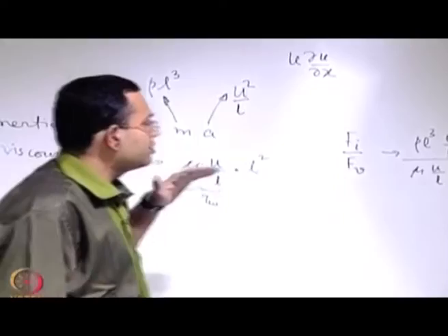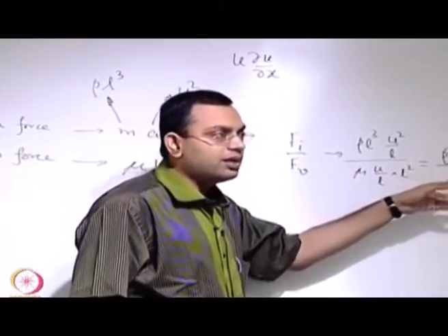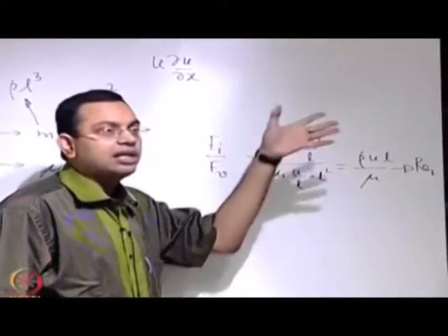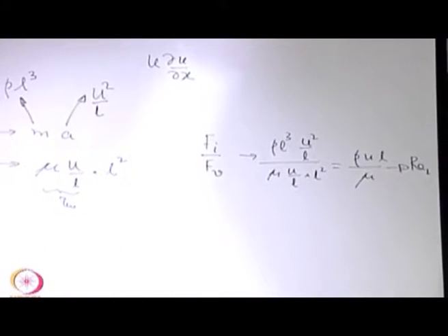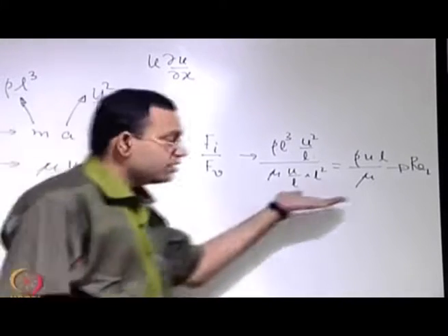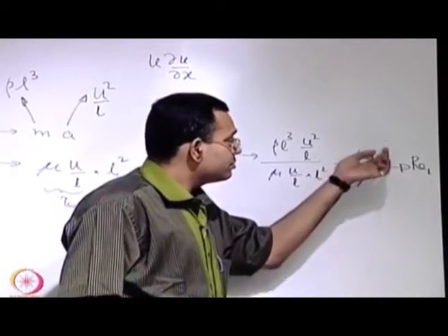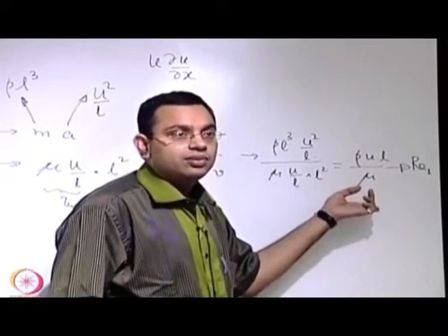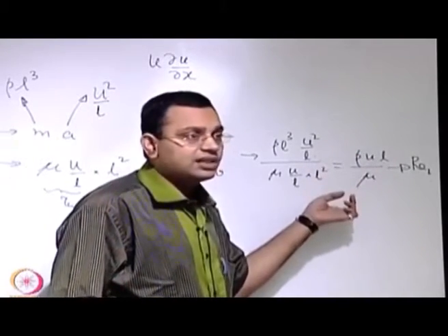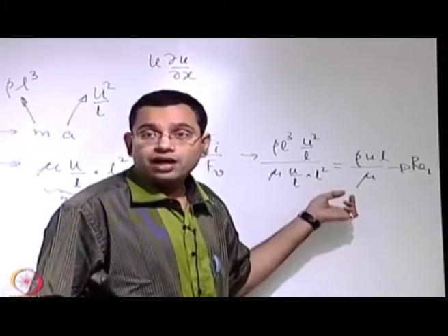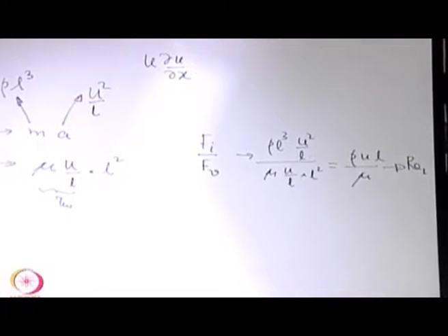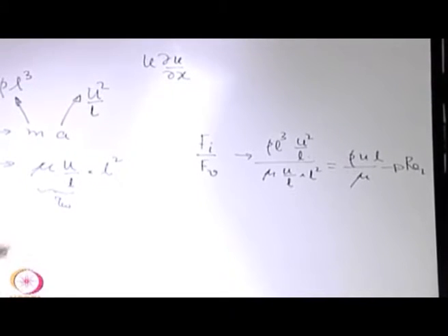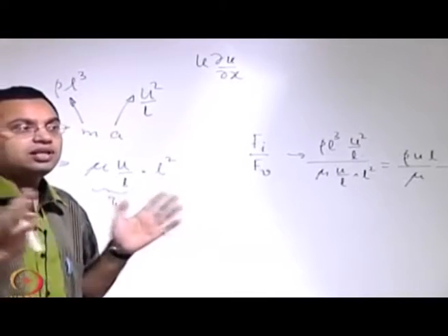So what Reynolds figured out is that, for flow through a tube or a pipe, if there is a critical value of this number, then beyond that critical value there is a transition of behavior from regular motion to apparently disordered motion, whereas if the non-dimensional number was less than that, then that never happened. The range of the non-dimensional number over which this transition took place was within a small range.